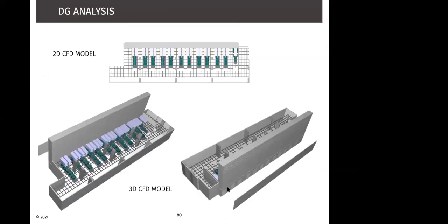In this case, the radiator air outflow is at the back of the room, and what has been considered is a shaft which is right above it with the air inlet provided on the same side. Now, this could cause short cycling of hot air from the radiator end into the air inlet, which could then be carried in by the ventilation fans and could increase the temperature within the room. So it is critical to study what delta T is being formed inside the room.